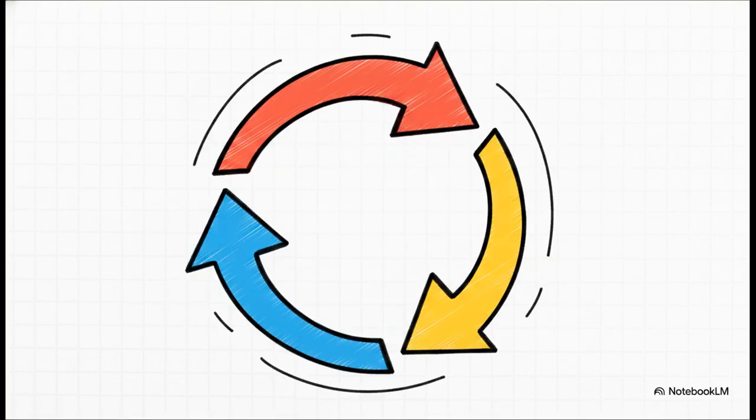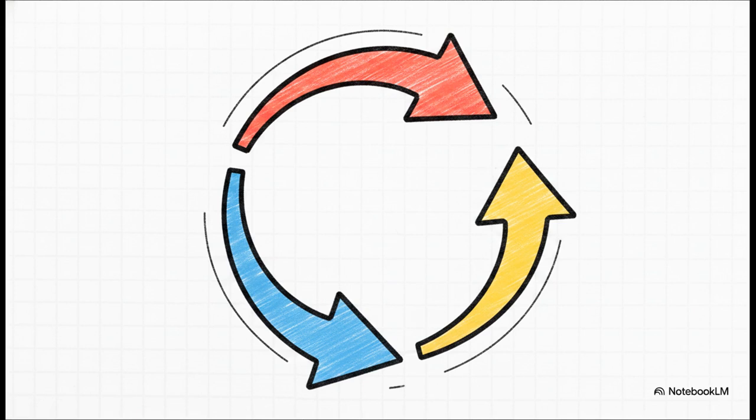When the voltage peaks in the order of red, then yellow, then blue, RYB, we call this the positive phase sequence. You can also just think of this as a clockwise sequence. And because it's a continuous, never-ending cycle, reading it as YBR or BRY represents the exact same clockwise progression. Now let's see how this builds.